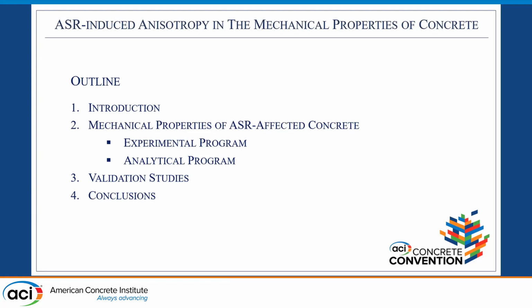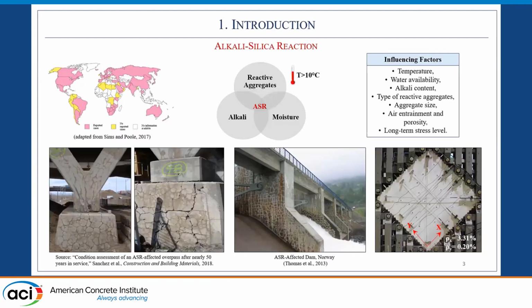Alkali-silica reaction, ASR, is a harmful deteriorating mechanism affecting the performance of concrete structures worldwide. It develops when the concrete mix contains reactive aggregates that are susceptible to alkali attack. The alkali hydroxides present in the cement paste react with certain minerals within these aggregates, causing a gel, which in the presence of moisture expands and cracks the concrete matrix. We can see in these lower images some crack patterns that we may encounter out there in infrastructure suffering from ASR.